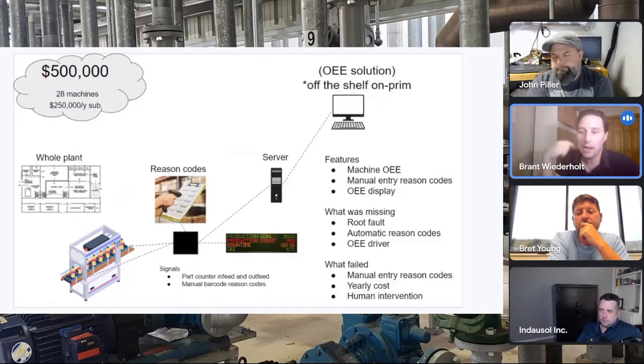So they're going to be cycling in and out, whatever. Getting somebody trained to do the right reason code when you give them an option, I think I'm starting to lean where this is a failed solution for the future. It's quick, and I won't say that it won't provide any value, but I think the reason codes. My argument is that years from now, or now, those reason codes need to come from the PLC, but that's just me. So it's automatic.